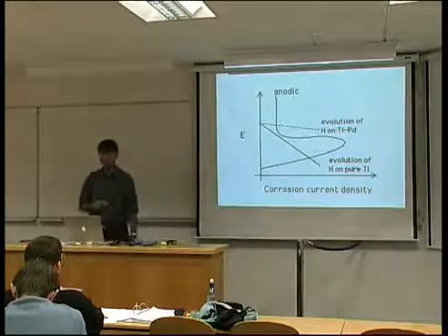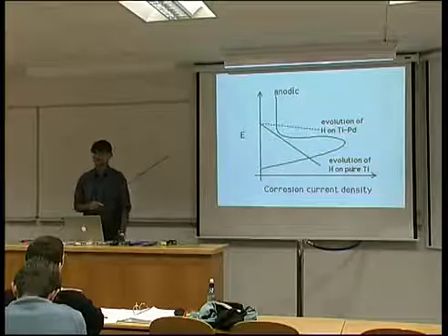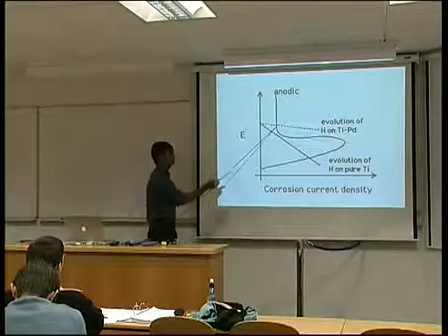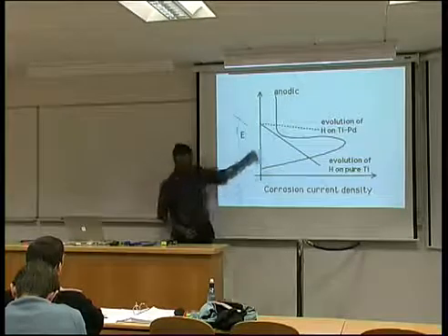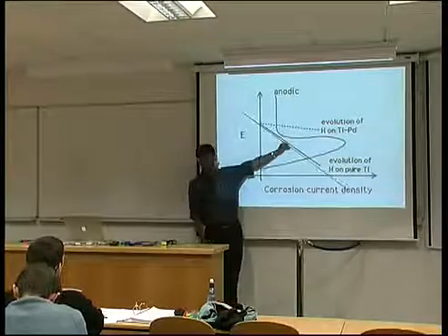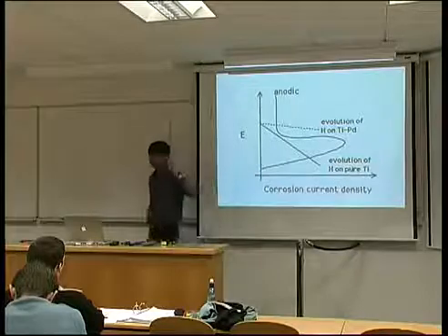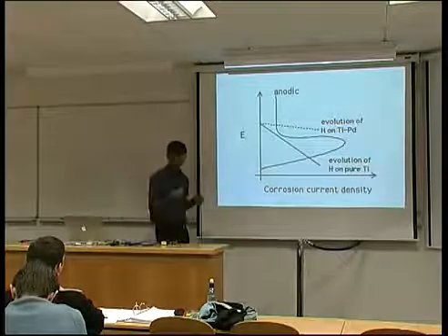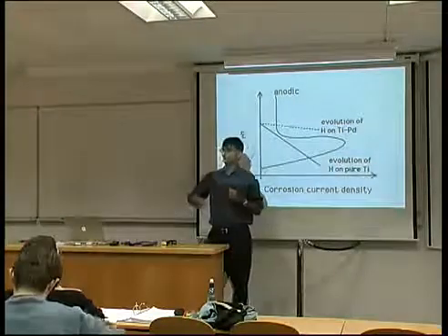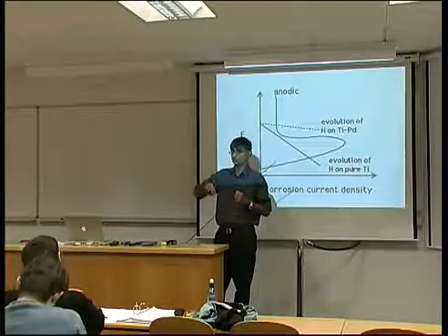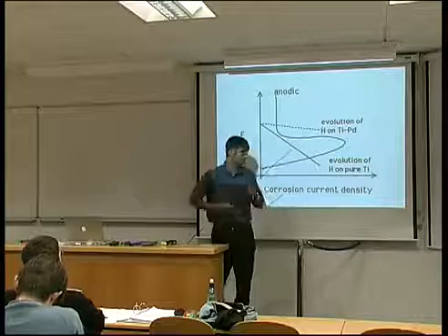Now that's too high, and we're not taking advantage of the fact that we can form a passive oxide film on the surface. So in order to stimulate this crossover to happen in this region, we need to reduce the slope of this hydrogen evolution. So if we add a small amount of palladium or platinum to titanium, then you know that hydrogen evolution on platinum or palladium is very easy, and that's why we often use those as reference electrodes in chemical reactions.